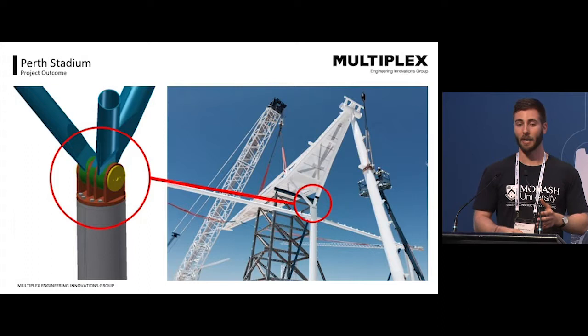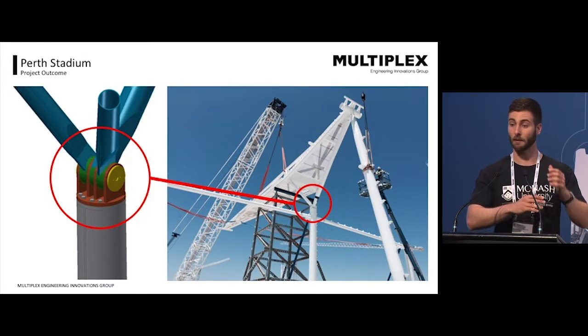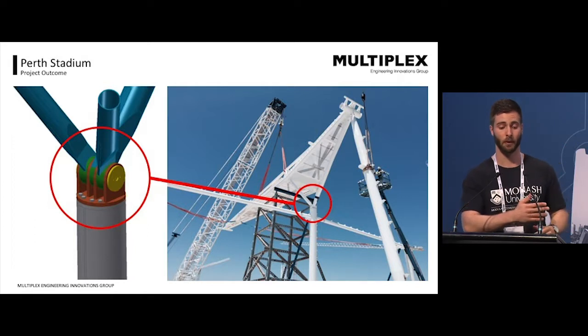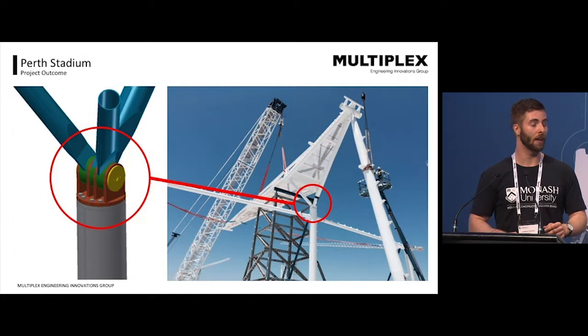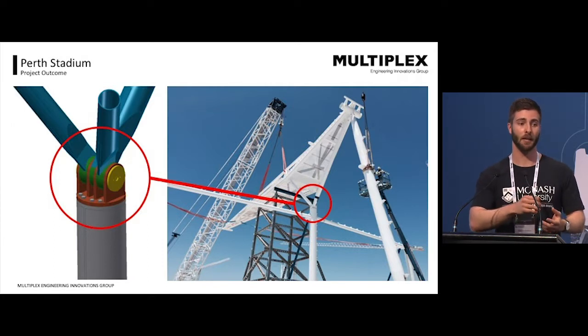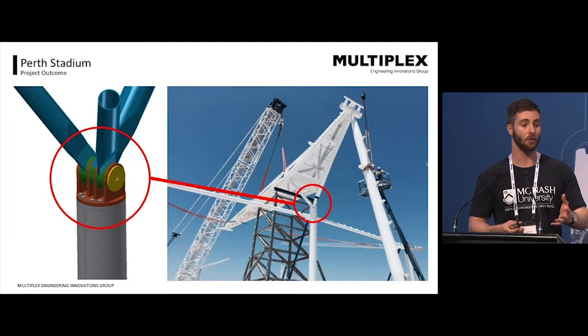And one of the big benefits about this connection was that we can actually have that flexibility in finally positioning the roof truss. So that rear member which we see going on there can be adjusted in terms of its height, and that adjusts the overall RL, or the overall position of the roof truss. And that's what we gain by actually having that flexible hinge connection there too.